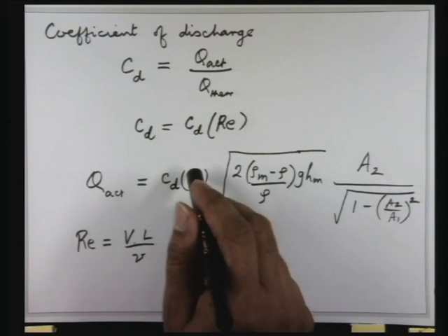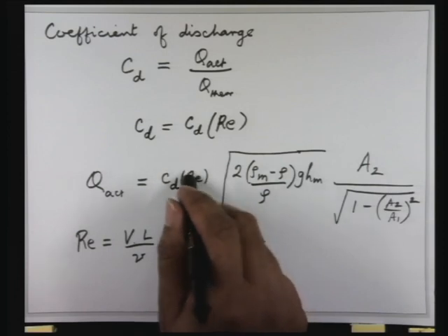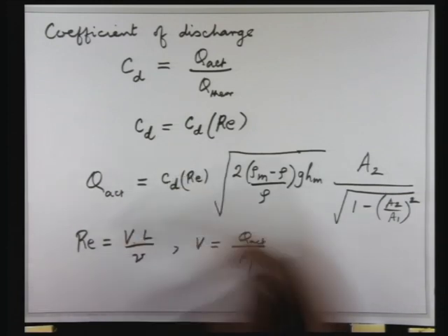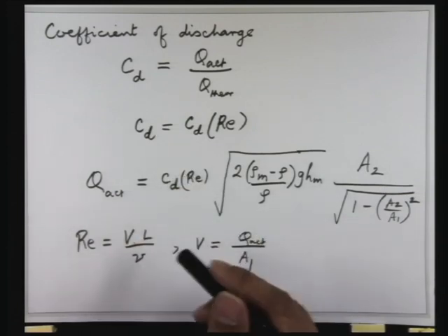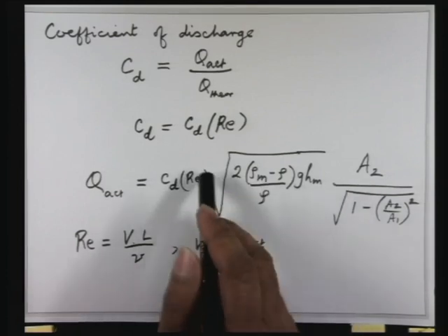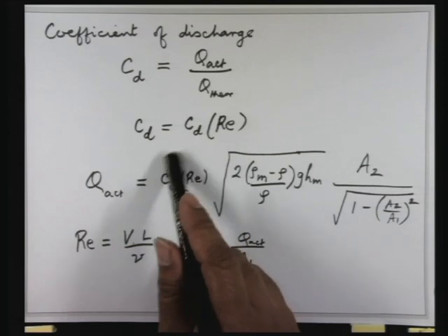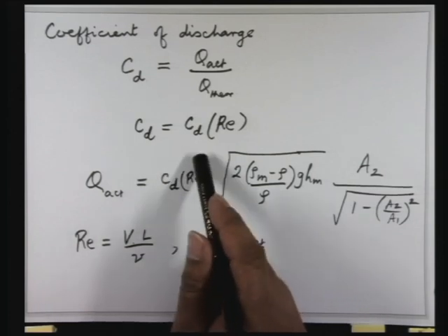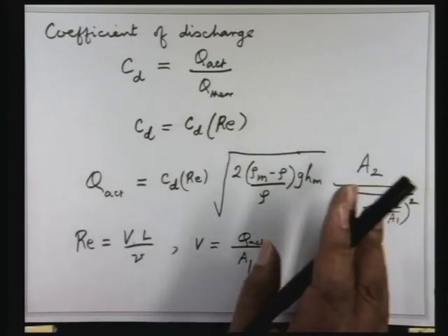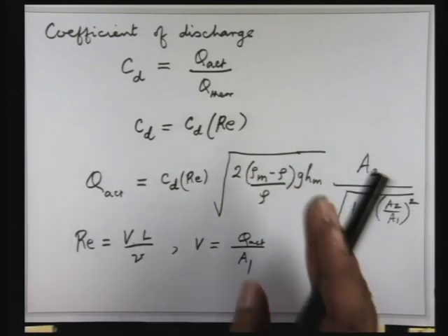So take the value when the Reynolds number is large, some constant value, and if the Reynolds number is large, then that is correct, so you don't have to iterate. But in principle, it can also be done iteratively. You have to first do a calibration experiment and fit a curve which tells you how C_D varies with Re for a given geometry. That is for the venturimeter which you are going to use.